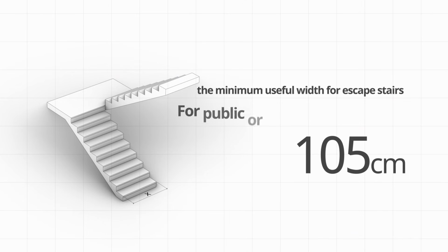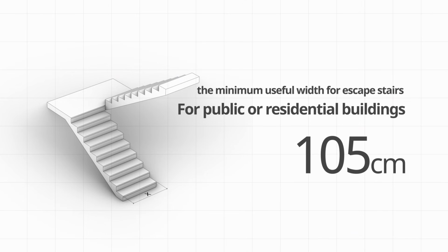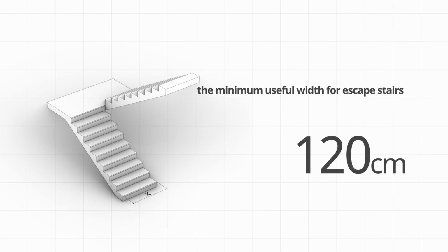According to Neufert standards, the minimum useful width for escape stairs should be 105 centimeters. For public or residential buildings with more than 2 units, this width increases to 120 centimeters, and in special cases such as hospitals, it can even go up to 200 centimeters.